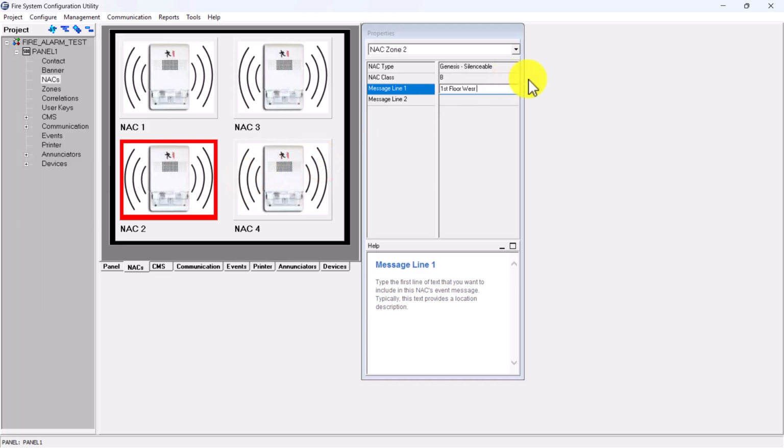So pretty much, another thing I want to add to the general alarm category will be door release. I don't want to add fan shutdown because the pull stations are inside of this group. So all I want to do now is just add the door release. So scratch that. We've got elevator recall and fan shutdown. So no door release.